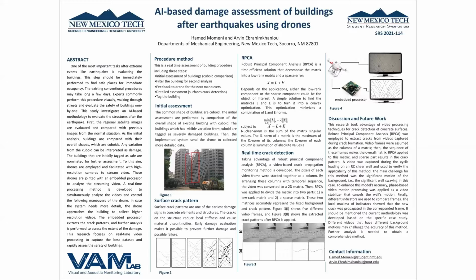For this method, we use robust principal component analysis as a real-time and time-efficient solution for extracting the cracks. And then we have the pattern as a sparse matrix. Then we can do further analysis to find the severity of damage. This is a real-time process. We need real-time processors to analyze a huge bunch of data, as high-resolution videos, to extract the crack patterns. And the main challenge here is this.